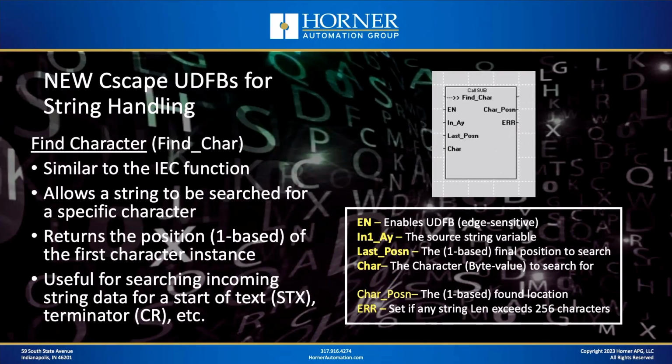Okay, and the last one we're going to talk about, the last of our 5 new function blocks, is the find character function block. Now, a few weeks ago, we did a session on some special data find UDFBs that we created. Okay, and this is very similar. So this find character UDFB is very similar to some of the UDFBs we talked about in those sessions, in that the whole purpose of this particular UDFB is to look inside of a string and find the first instance of a particular character in that string.